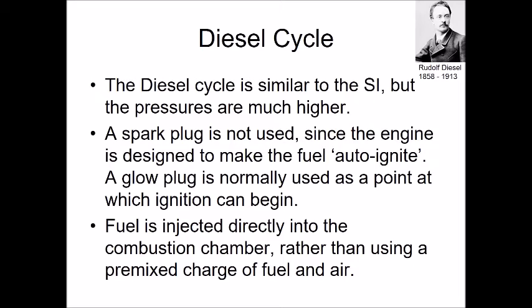So if you've ever driven a large diesel engine or a fairly old diesel car, when you get in them, you turn the key and a little light comes on, and it sort of is saying to you, hold on a minute, I'm just warming up. So what's happening is the glow plugs are warming up. With more modern engines, they tend not to do that, but that's how a diesel engine works. It needs a glow plug just as a starting point for the ignition. But normally they will just light up themselves as long as the compression is there.